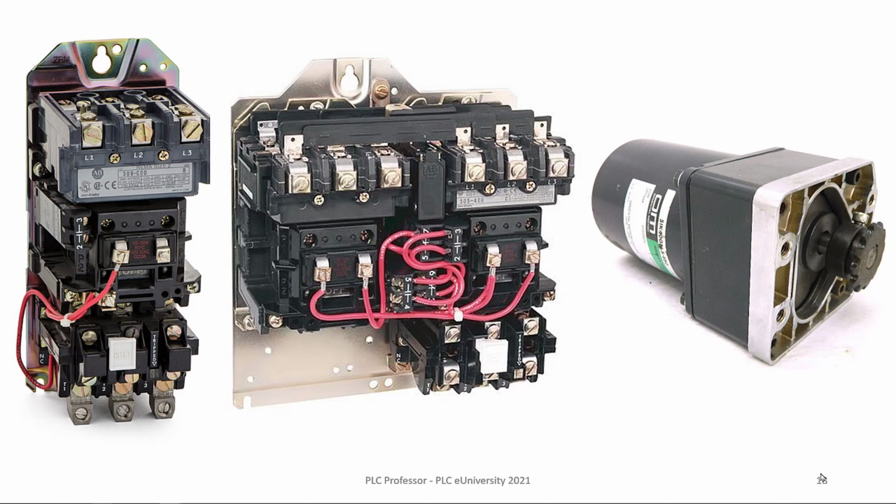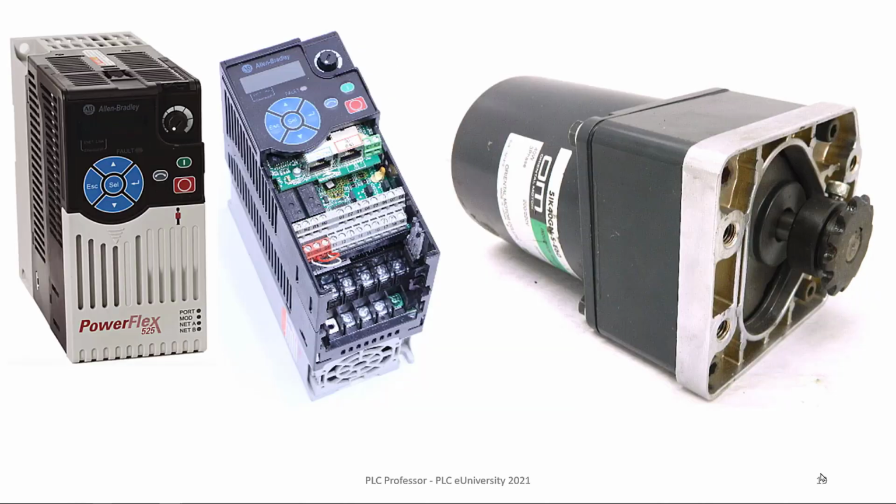And the speed of the conveyor is going to be 1720 divided by the gear reduction between the gearhead and the ratio of the sprockets going to the conveyor. It's just fixed speed. However, if you want to control the speed and the direction and accel and decel, sometimes you don't want the conveyor to start up with a jerk.